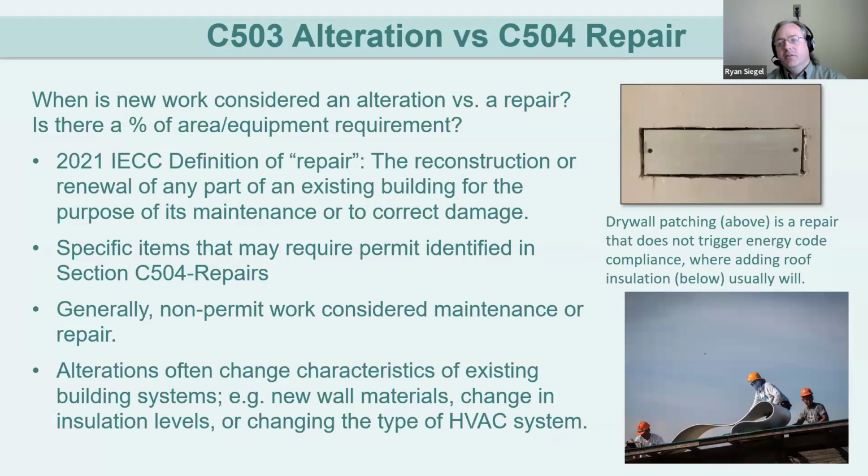So recognizing when I have a repair or when I have an alteration, the code does not call out a specific percentage threshold. Your local jurisdiction may have a threshold where they say beyond this, that's no longer a repair, that's really an alteration. But the code is really looking at repairs saying, we're doing reconstruction or renewal for the purposes of maintenance or to correct damage. So as we see on the right-hand side of the screen there, that drywall patch, someone may have damaged the wall, and so we are making a repair to fix that damage or dent that had been made into the wall.